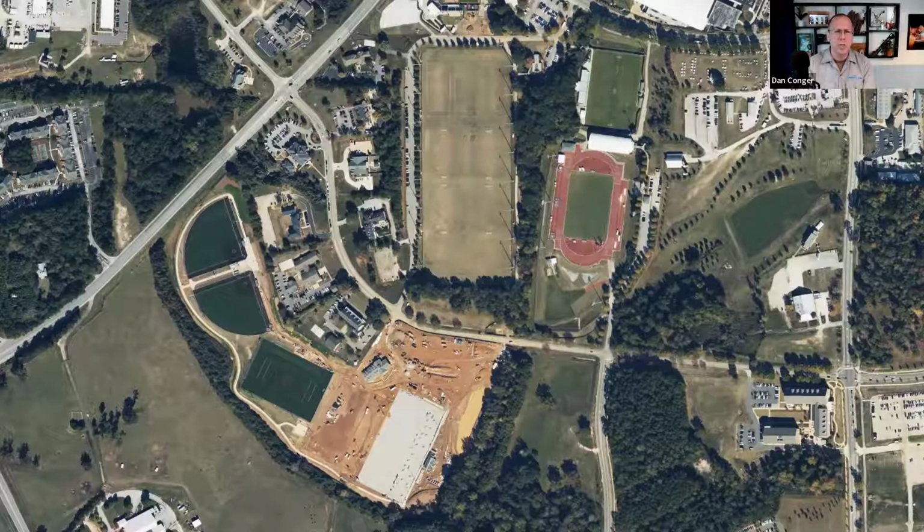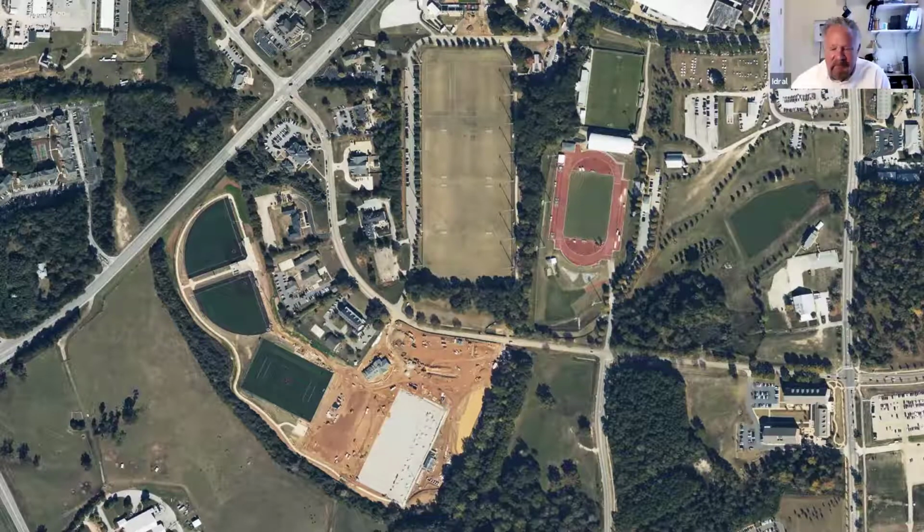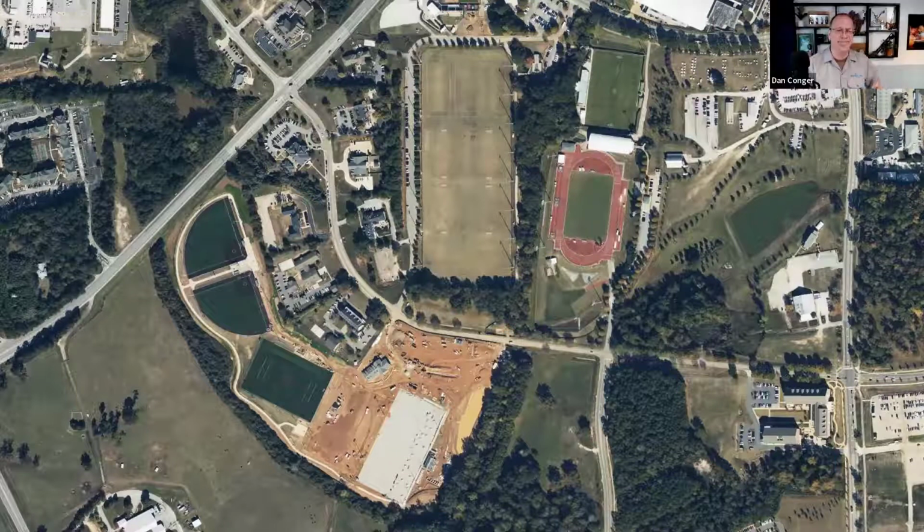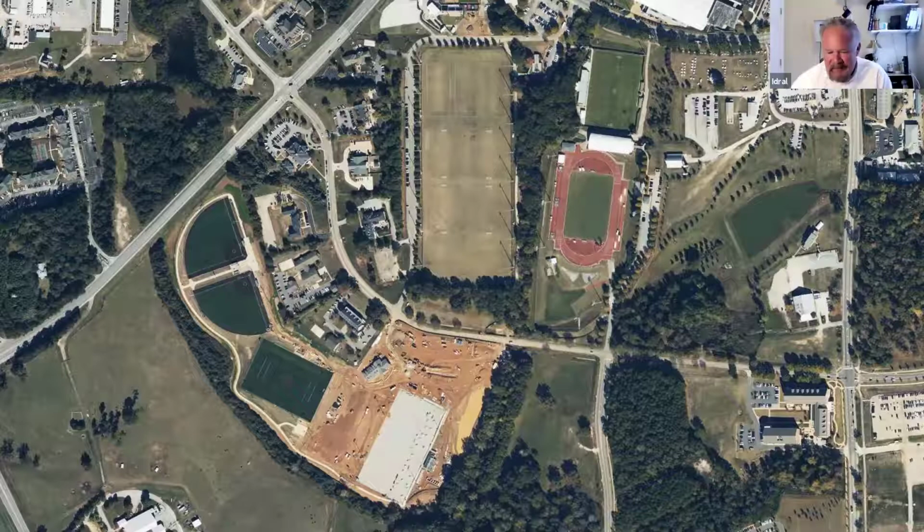Okay. So their plant material, it sounds like we had grass, turf, shrubs, traditional irrigation and traditional plant material, but then that artificial turf, right? They wanted to keep that wet. So what were they using to water that down and keep that going? They're using the large Hunter in-ground turf rotors. They use about 250 gallons a minute, and they're used basically to either cool down the turf, or to rinse it down with high volume amounts of water. They have a 12-inch main line that's looped around the artificial fields, so they expect high water usage.